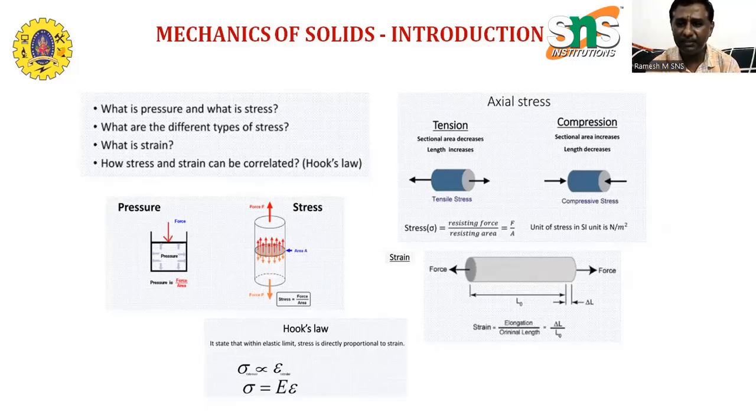This can also be converted into stress. Generally, factor of safety is equal to ultimate stress to the working stress. Even though it is designed for one man, we have the factor of safety as a design factor in order to avoid fracture. So the factor of safety is more than 1, such as 2 or 3, and based on the applications we fix it here.